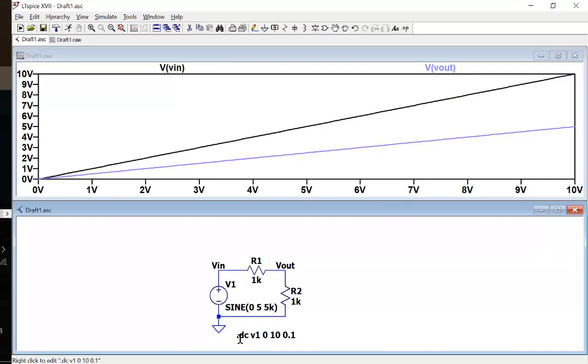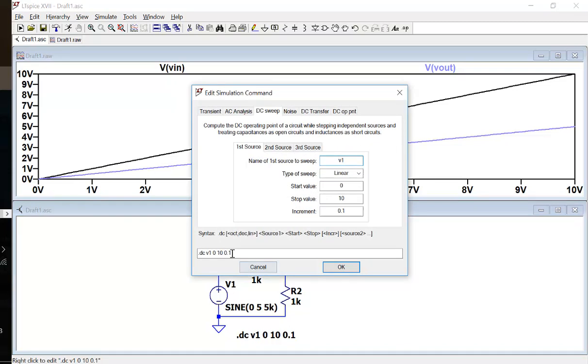And now, can I still sweep it? Maybe, but I don't want to do that because I just want to see the sine wave. So when you plot a sine wave, what is the x-axis? Time. I show the sine wave on the oscilloscope, so the x-axis must be time. So you need which kind of analysis? DC sweep? The x-axis is what? Voltage.